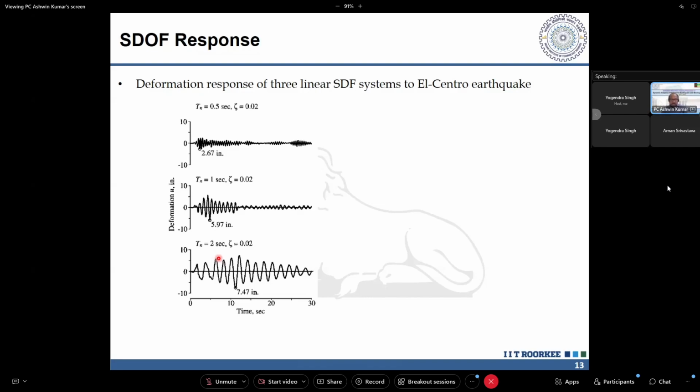But what is the other trait that you see? That for all of them the damping ratio is the same. So we have single degree of freedom systems in which the damping ratio is the same. They all three have been kept on top of the table, and we are measuring the peak response of the system when it is being subjected to a ground motion.